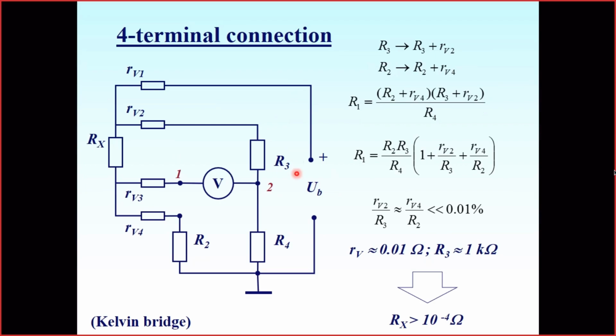If they differ, it means that we have somewhere in the bridge a source of thermoelectromotive force, because, as I said, two different metals are connected together in one contact. Then either we take this error into account by applying some correction, or we just make the measurement changing the polarity.